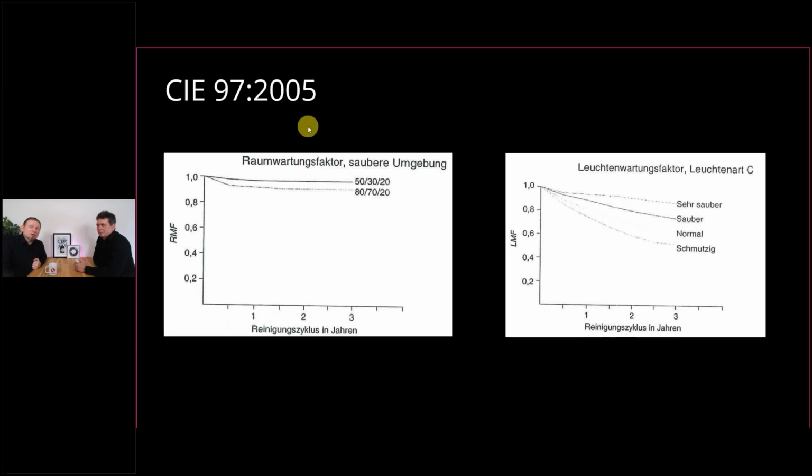There was also close to a decade where nobody was really knowing what the maintenance factor in LED was about. So some guys were assuming, okay, LEDs are never going out, the survival factor is always 1, and the lumen loss is quite low on LEDs. They last forever, so we just put 1 into it. This is wrong. There's also a degradation of the output of an LED light, and that has a lot to do with quality and with lifetime and so on.